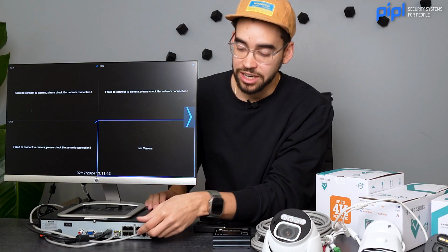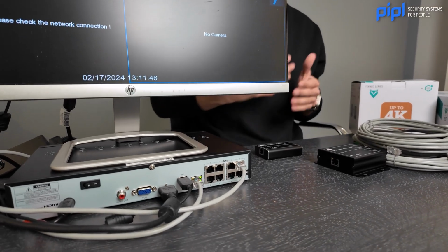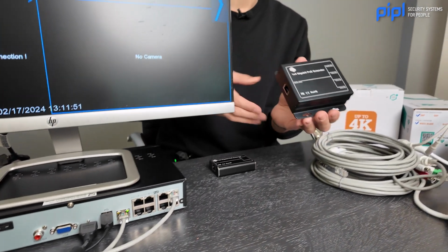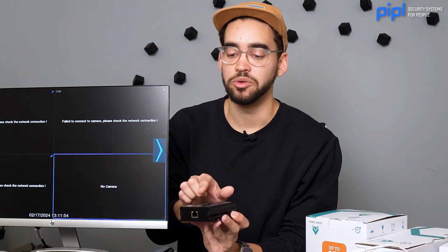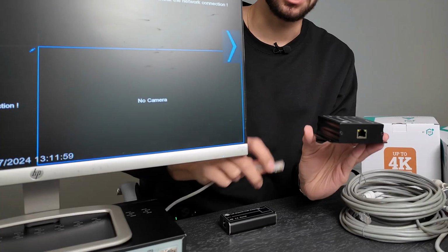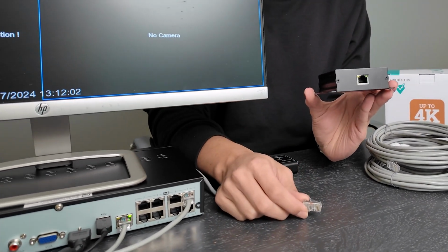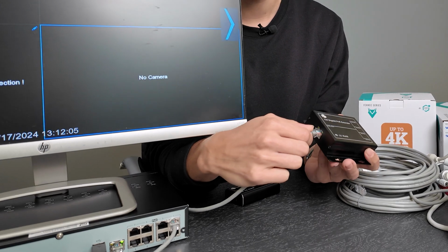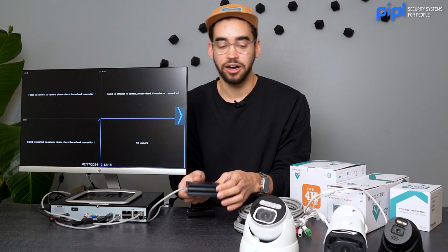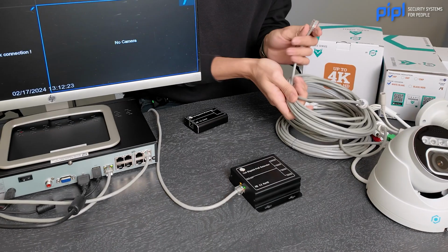From there, you connect another Cat5 cable inside the PoE switch, and this is the one that will go inside the PoE extender. So you take the PoE extender, as I mentioned before, you have the PoE input right there. You take your Cat5 cable that is right now on the port number 1 of your NVR, and you connect it. So as you can see, the lights turn on. That means that power comes through your PoE extender. And now, well, I have multiple cameras on the table. We're gonna power 3 cameras that have different power outputs. And it's as easy as this.